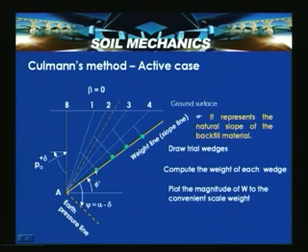Now, from these points, draw a line parallel to the earth pressure line, that is this line. Draw the line and see where it cuts: that is the point A2, this is the point where it cuts, A3, and similarly this is the point A4. Joining these, we get the Coulomb's envelope. This is nothing but the earth pressure locus.